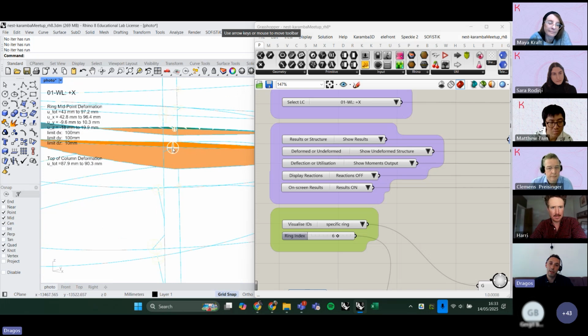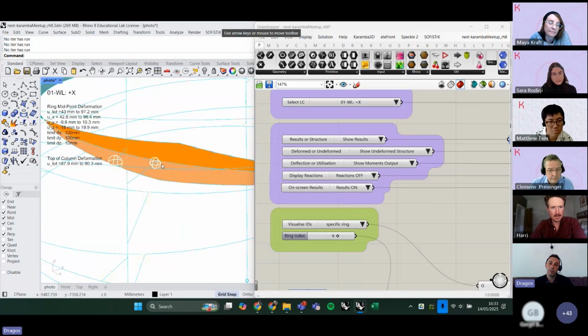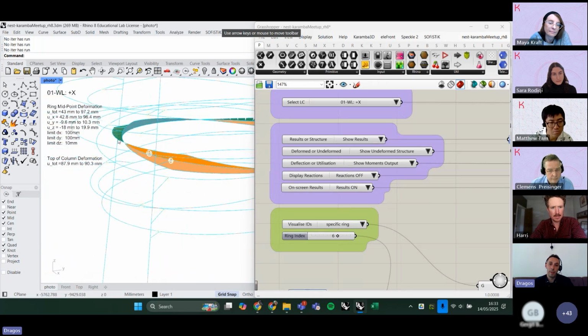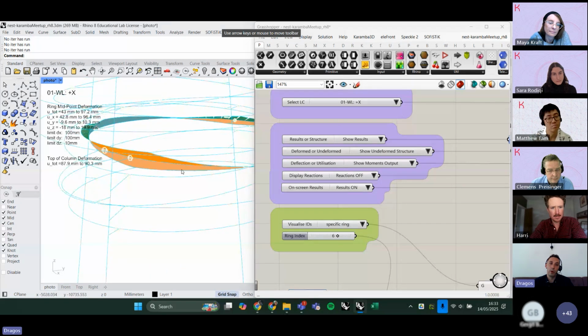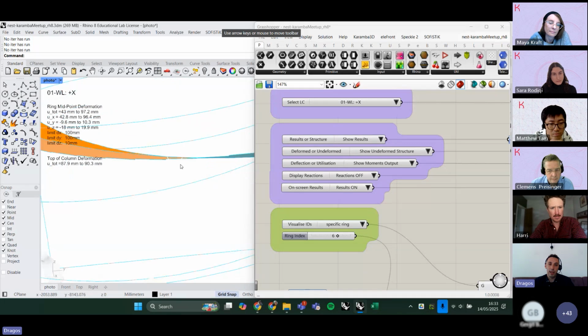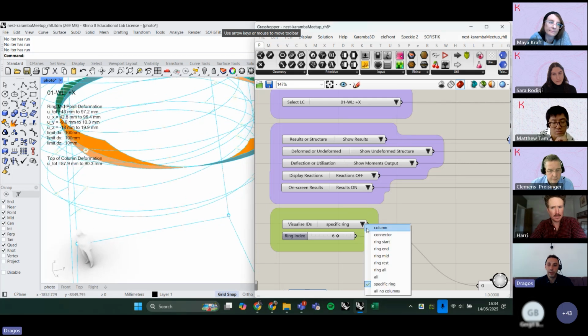So basically the arc is mounted on a pin on that, and it can rotate, but it is continuous throughout that location. So all four locations. But we did put a release into the plane of the ring. So at the splice location, it's like a pinned arch there in the plane of the ring. So it's not carrying moment through there.